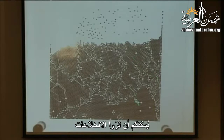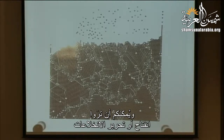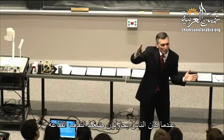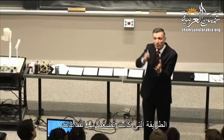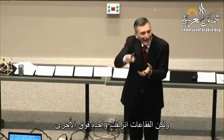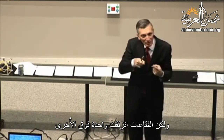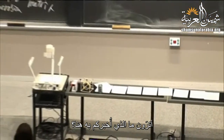You can see dislocations, everything, and I know he showed you at the end the Bragg bubble raft, and you could see the dislocation zipping when people were trying to compress the bubble raft. The way the bubble raft was compressing, the bubbles didn't all get flat. The bubbles glided over one another. And the dislocations relieved the stress. See what I'm telling you here?